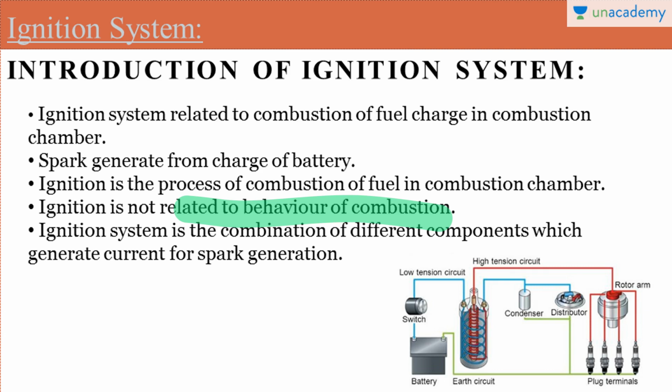And the energy which is supplied from the spark plug to the fuel charge, or the fuel air mixture, will burn the fuel, and this particular process will change the chemical state of the fuel air mixture, and will release the chemical energy, and this chemical energy will transfer in the form of thermal energy in this particular ignition process. So this is about the ignition process.